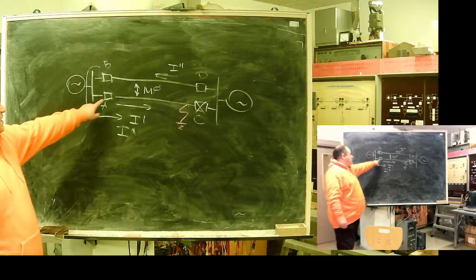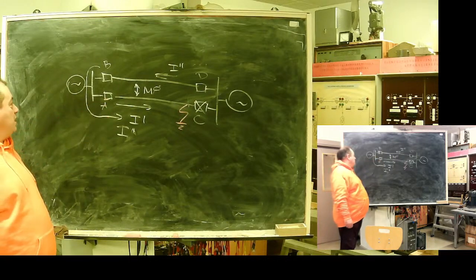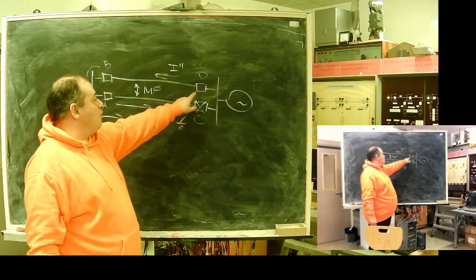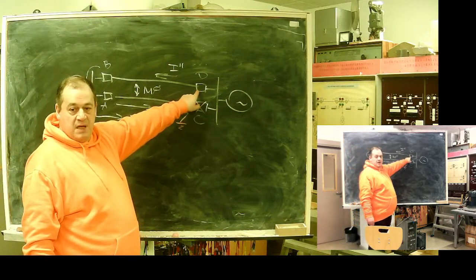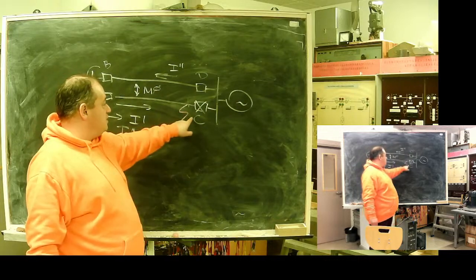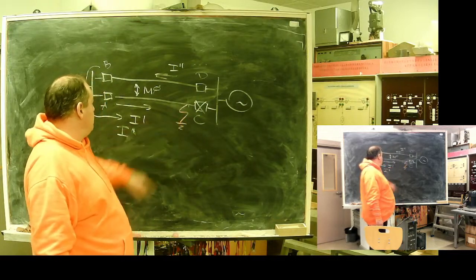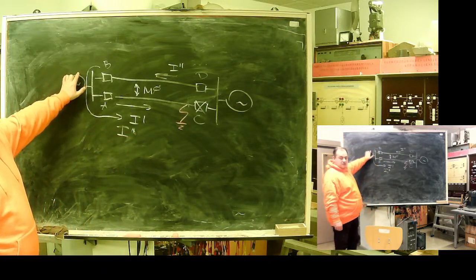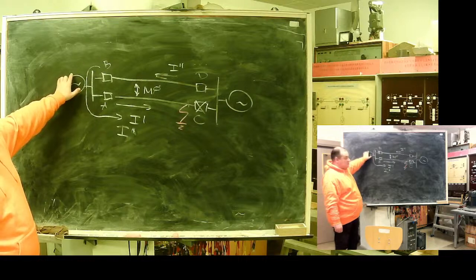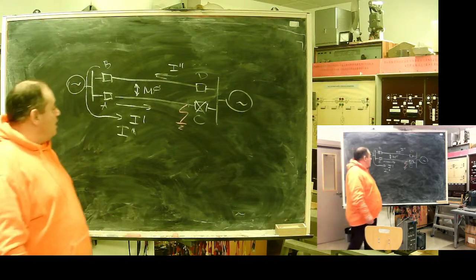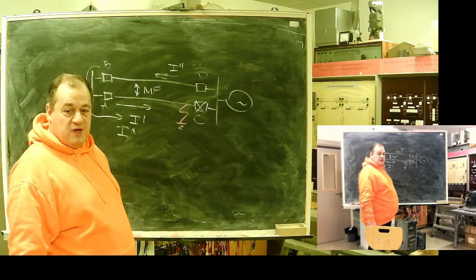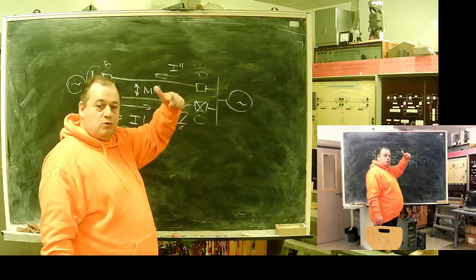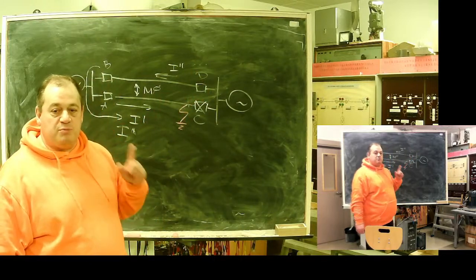For our relay here it's fine, but the same thing happens also for D relay. D relay sees this fault through this loop. If the source is small or not present at all, a bad thing can happen. Fault for this relay may go into operation zone. So this should be checked.